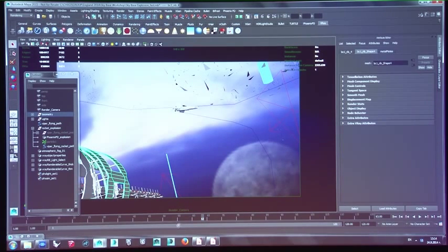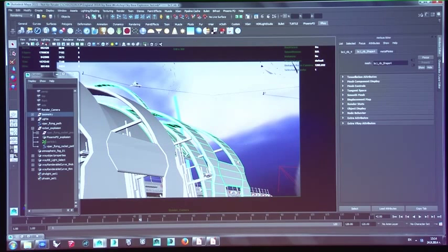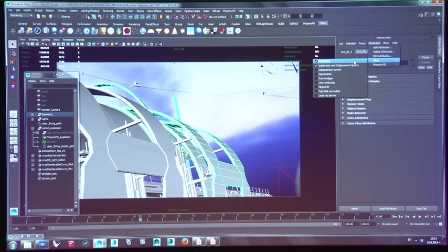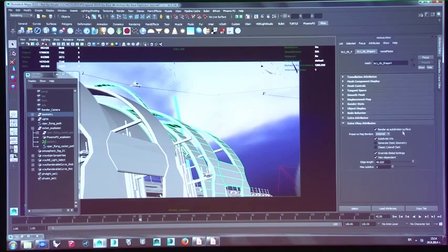For this, you can just select the object or a set of objects, and in my case, I have applied a custom V-Ray attribute, which is V-Ray subdivision, and gave it the controls for the subdivision. It pops up here at the bottom. So I can have it render as a renderable surface, which means exactly what it sounds like. This is going to be subdivided only at render time. So in the viewport it is going to be the low poly version, but when I render, it's going to be really, really smooth. And to prove my point, I'm going to render.